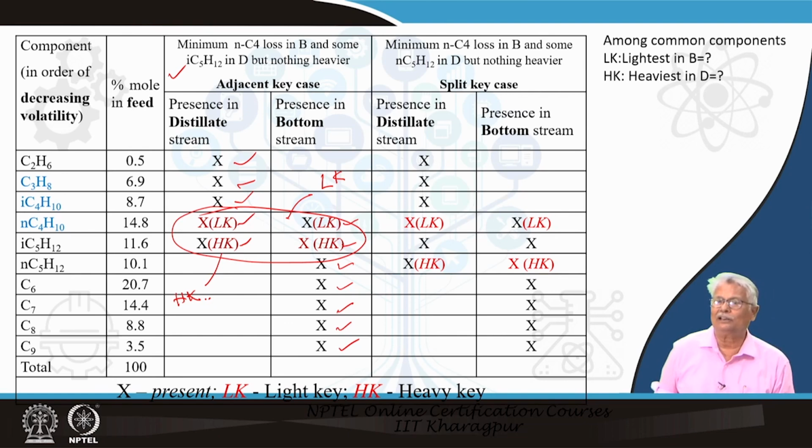So, can I say, or can you appreciate at this particular point, that the LPG, which is a distillate stream here, in the left case or case 1, is not going to contain any NC5, while in the right side case or case 2 it is going to contain this. So your LPG is going to be purer in the first case and relatively impure in the second case. Quite naturally, you have an extra yield of LPG volume of production in the second case.